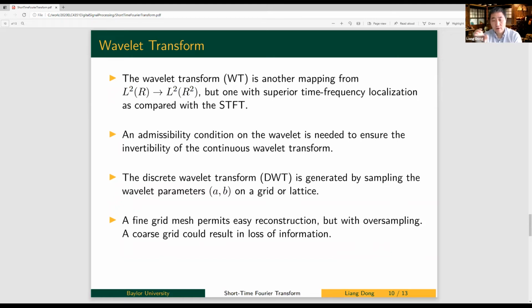This magnifier not only shows the signal to find the frequency, but also localizes it in time. So we can really use a wavelet as a very good magnifier to examine and analyze signals. The concept follows the short-time Fourier transform, so it's easy to explain and easy to understand.